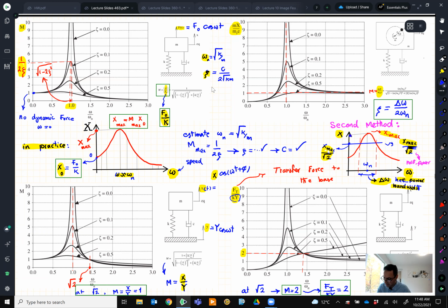So from Jenny, this is exactly one of the many things in vibration diagnosis. In vibration diagnosis, I will talk about it again toward the end of the course. People use an accelerometer. They put the accelerometer on the machine and do measurements. It depends on many things. You then get these graphs. You realize if you need to add mass, if you need to add stiffness, or if you need to add damping.